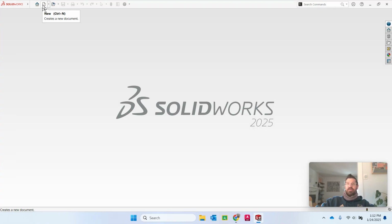So I'm just going to go through some of the things with you. I'm going to highlight a couple of things. I'm going to highlight the importance of fully defining your sketch elements, your shapes, because it's going to be important when we come to try to make three-dimensional shapes out of those sketch profiles, those contours, right? That's going to be the main thing I'm going to highlight.